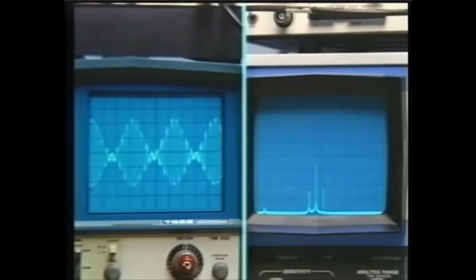We have only the two sidebands, and the signal is now highly overmodulated. We bring the carrier back up, and when we do that, then we are reducing the percent modulation, and simultaneously, obviously, related to that is changing the carrier level.